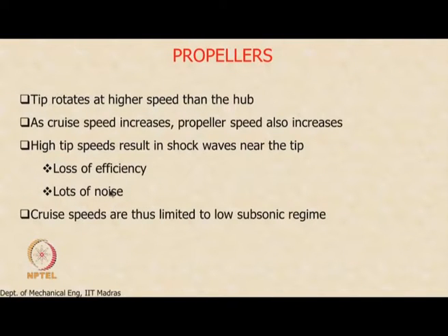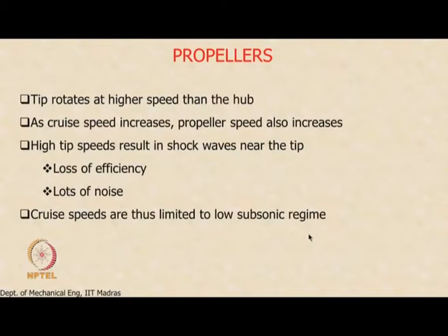The other disadvantage with the propeller engine is that it is very noisy from a mechanical perspective, because the propeller is directly, mechanically coupled to the gas turbine engine shaft. It produces a lot of noise that you can see even today. If you fly in a turboprop, it is extremely noisy even inside the cabin. For these reasons, cruise speeds of turboprop engines were limited to about Mach 0.5 or so. And Mach 0.5 is simply not a viable option both commercially and from a military perspective.